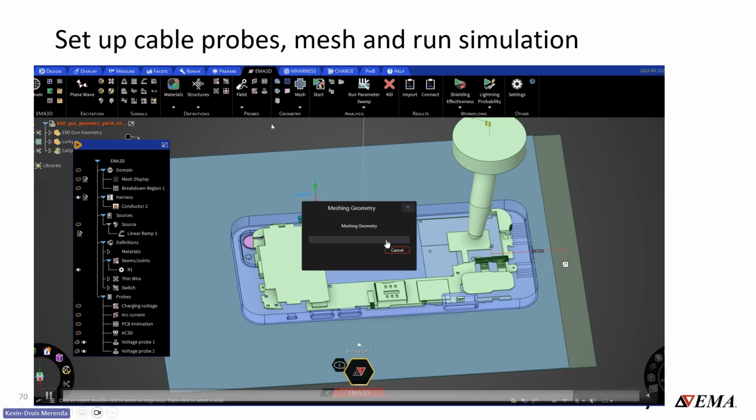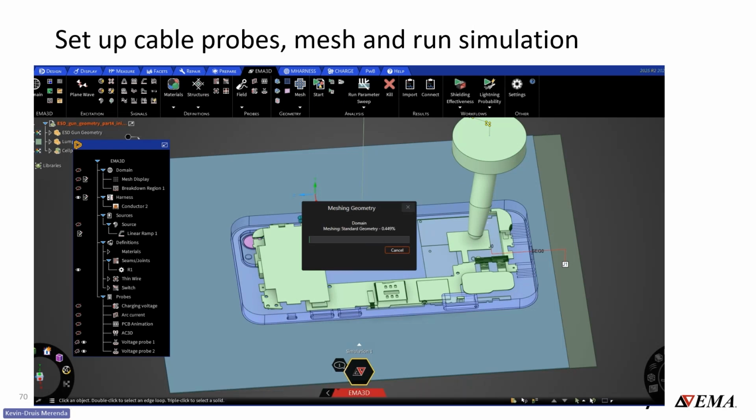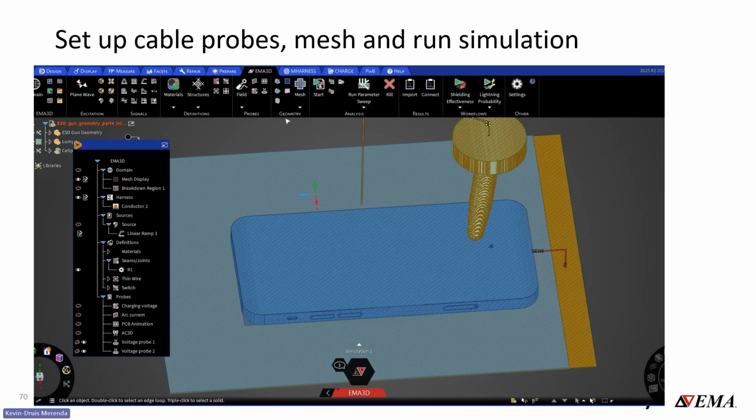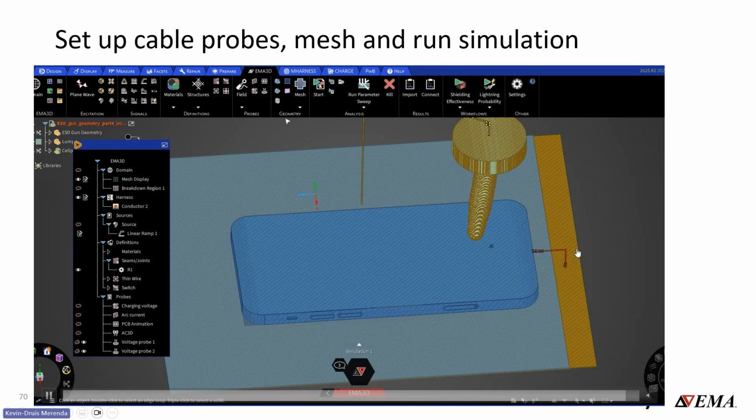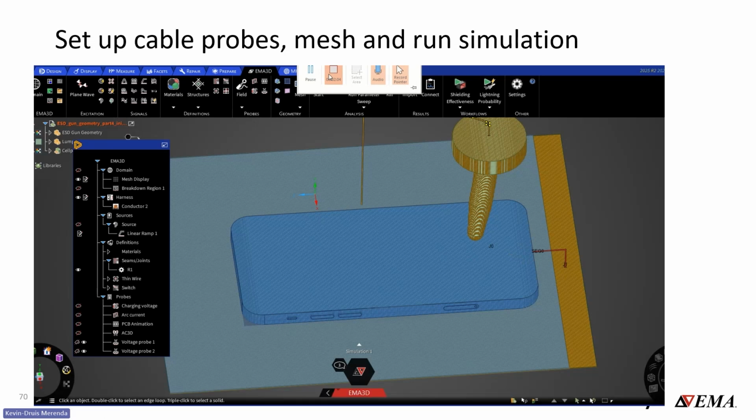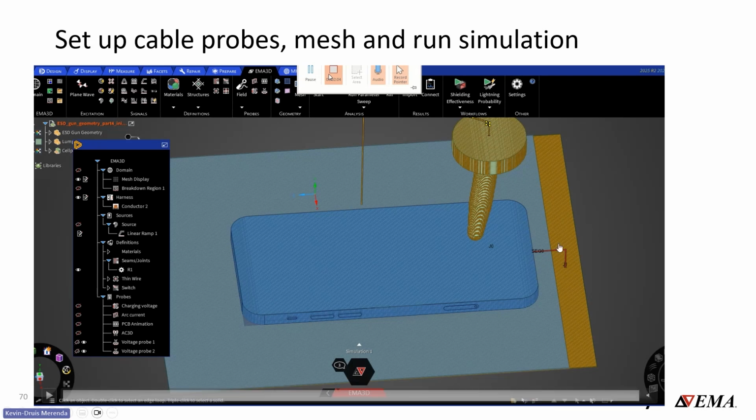When we mesh this, just like we did thin wires, we have to mesh the harness, and it's a linear element mesh. As you can see here, we have a line that is meshed explicitly, which is going to be the path of where our segment is present. We have some rules on how this segment and cable can interact with the rest of the geometry. So there are some deconfliction algorithms inside our mesh engine to be able to handle the path of the cables through the mesh geometry. These are part of some of the typical tutorials for EMC Plus, and we can definitely explain how these methods work, depending on some of the routing that you may have in your system.